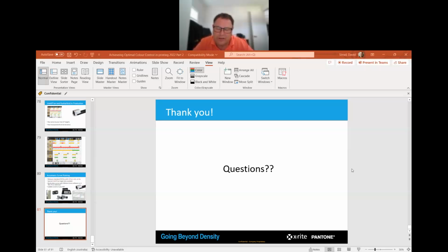A lot of that will come down to understanding and specifying the correct standard through the process. So if your output color on press is not the color that's where the ink is being proofed, and even down onto the substrate that the ink's being proofed onto, and understanding the film weight that ink's supposed to be printed at when you're formulating the ink in the first place, are key things that you need to understand.